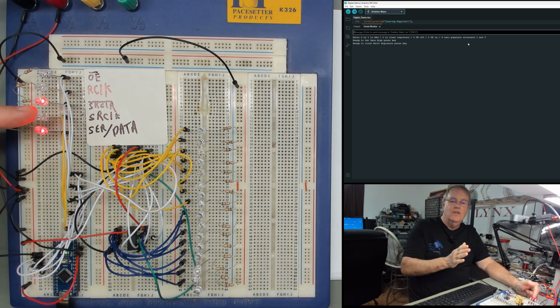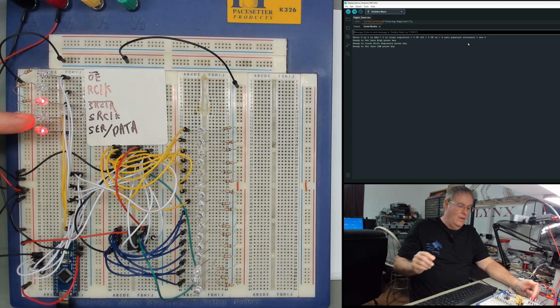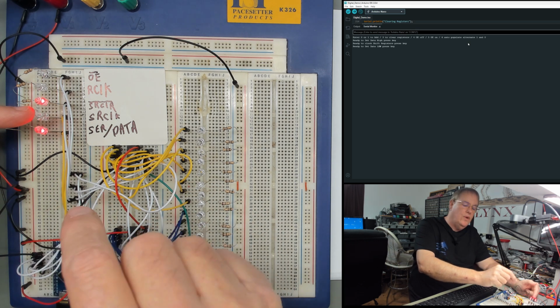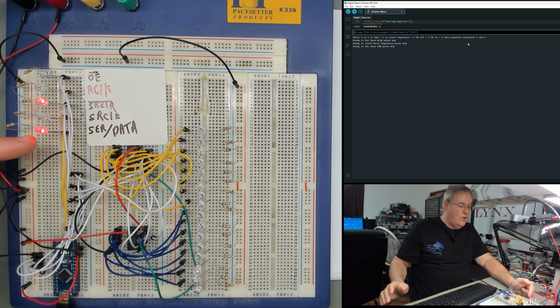This is not then shifting what's in the shift registers out to the actual storage registers. So let's tell it go ahead. It went high, it went low. That clocked the data in. So right now the first shift register on that first chip has a 1 in it. Now the storage register doesn't have anything in it because we haven't put it there. Now it's ready to turn this back low again. We don't need it high anymore. So I'm going to go ahead and do that.